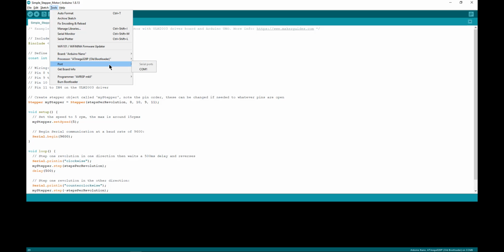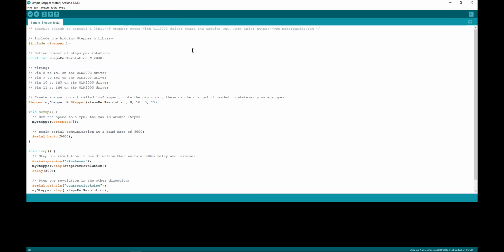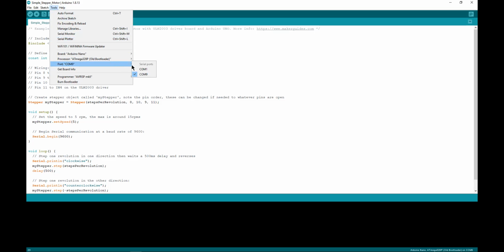And then when we connect our Arduino Nano, hold on, where is my plug? Without the driver, normally you would not be able to read the Nano. But with the driver, when you connect the Nano and the computer, it should show up. Actually, plugging it in right now. Yeah, there we go. It should say COM9. It might be different for you. Once you plug in your Nano, it should pop up automatically. Select that.